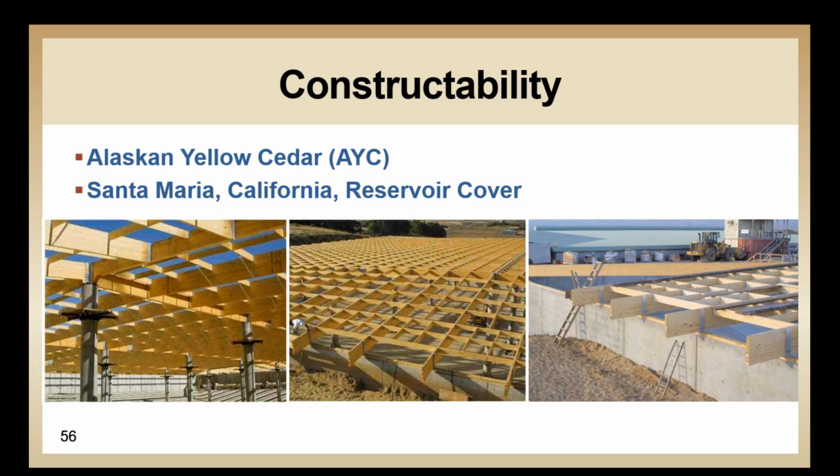So the heartwood of Alaska yellow cedar, with its natural resistance to decay and longevity, was a clear choice for framing members. The roof was constructed using Alaska yellow cedar glulam members with beams up to 8.5 inches wide by 25.5 inches deep, with the longest beam being 62.5 feet, spanning a 56-foot opening.